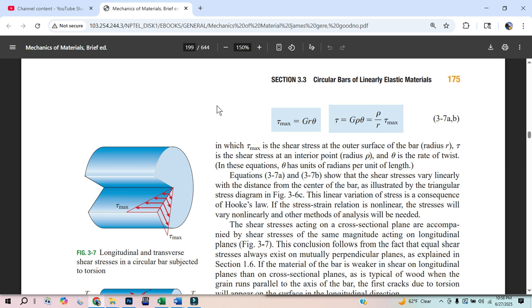If I have a rod that's in compression and apply a load, am I applying the load evenly on that top surface? I don't know, maybe not. If I am applying a concentrated load, maybe. It takes some molecules to actually distribute that load so that every slice then has it. And the same thing could be the case for welding on a little bar here and then torquing it. You might have to go into the rod at least the diameter to have that be uniform.